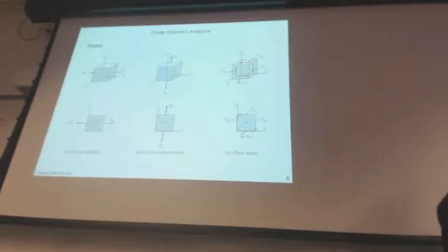So when we're talking about transverse shear, we're dealing with an object that has bowed. If you take, as an example, two boards and put them one on top of the other and you put a load in the middle, they'll obviously bow in the middle. But if you look at the ends, they don't line up anymore because the boards have shifted slightly. That is an example of transverse shear.